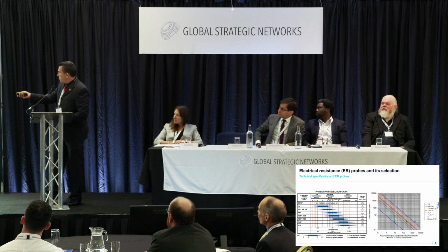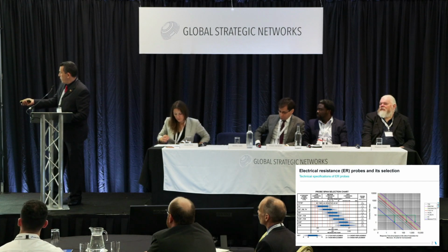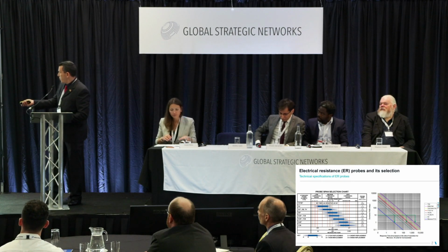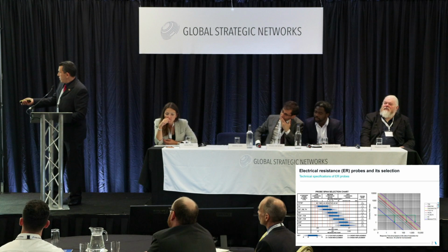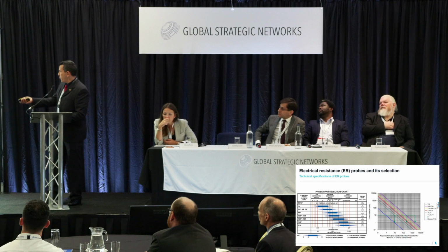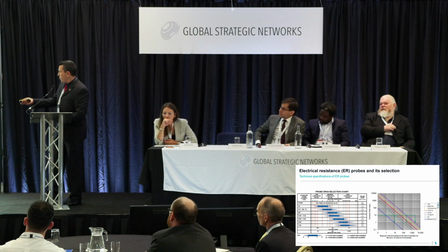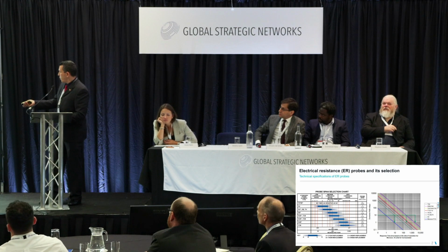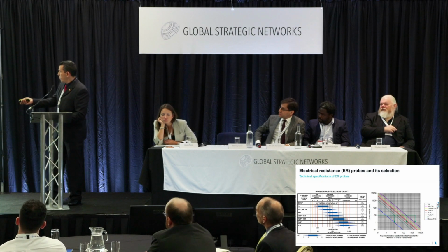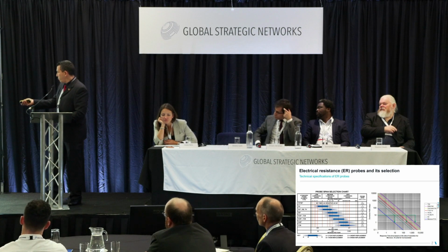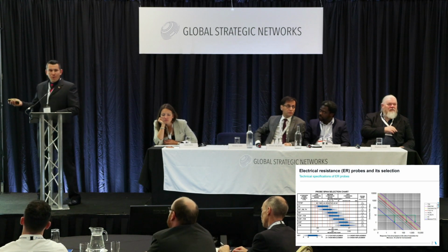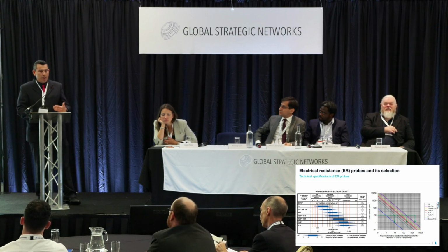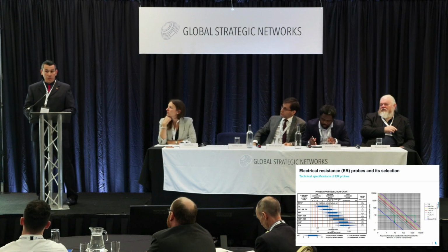And for this type of probes, you might have to exchange them maybe every 6 weeks or 3 months. The range between A and B, as you can see here, they might last 2 years, 1 year, and if you're coming in this range, meaning that you have a high corrosion rate and you also need a short response time, you will fall into the range C-D, meaning you will have to change that probe every 3 months or every 6 weeks. And this is not coming only from the suppliers. This is information that I have backed up from real situations.